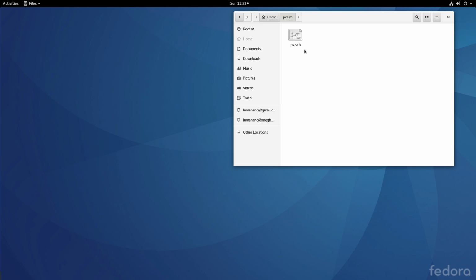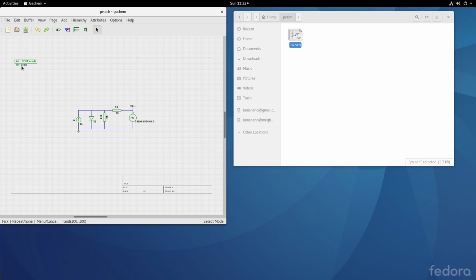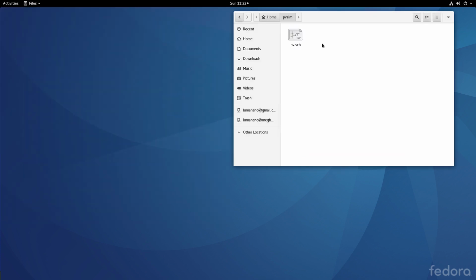Before creating the netlist, there are two files that need to exist in this folder. One is the pv.sub. Recall that we had mentioned pv.sub here in the spice include directive. We need to provide that file even if it is a blank file. And the other one is pv.cir, the circuit file, which will contain all the analysis that ngspice is supposed to do.